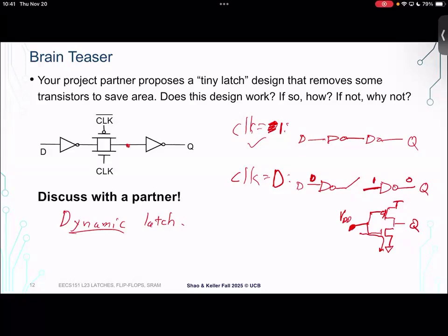So there's gate leakage forward, and then there would also be leakage backwards between the source and the drain of the transmission gate, even if that transmission gate is off. That's probably the more substantial leakage path to worry about in this design.